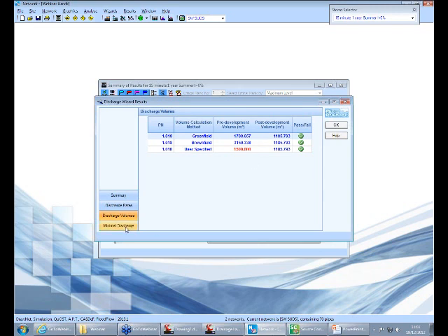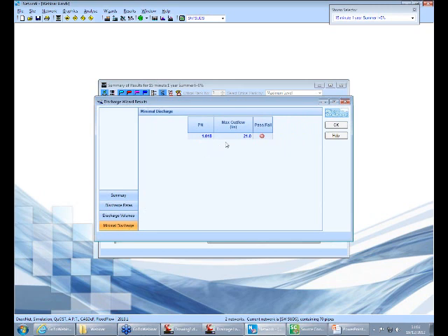Looking at the minimal discharge, we have the one failure here, and that is the fact that we are discharging a rate of 21 liters per second from that outfall pipe, and to gain credits with the Code for Sustainable Homes, for example, we would have to have 0 discharge. So no prizes here, folks, but if you wanted to post as a question an answer as to how you can actually manage to have a max outflow of 0, that would be most welcome, because we can share that with everybody. Okay, I'll say okay to that.